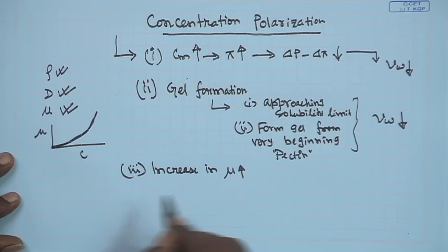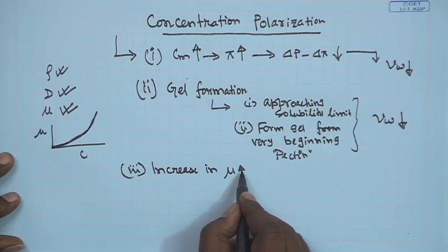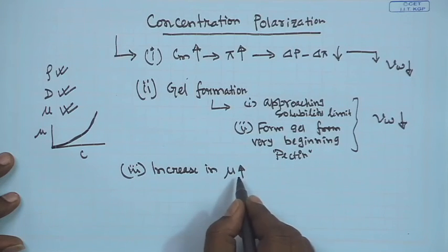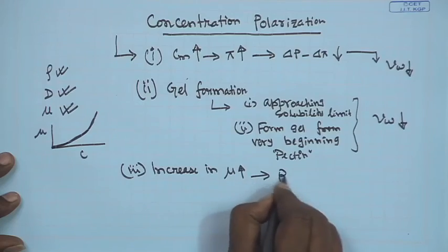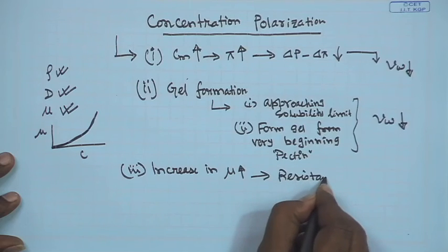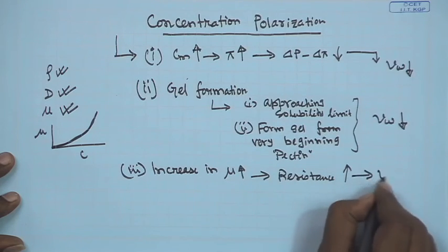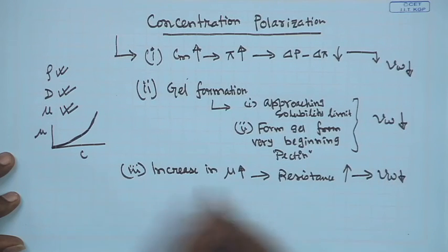So, in that case, the viscosity suffers a lot. In fact, viscosity increases tremendously within the mass transfer boundary layer. So, what does an increase in viscosity result in? It results in a very thick, highly viscous solvent near the membrane surface. It offers additional resistance, so resistance against the solvent flux increases by increasing mass transfer resistance, and the result is a decline in permeate flux.